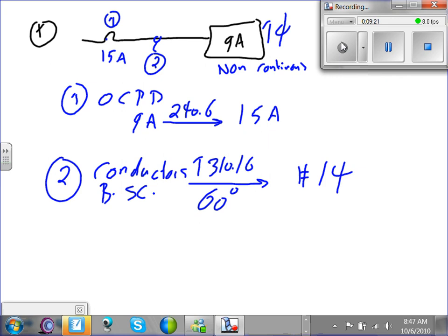If you take a hot and a neutral, what system is that? Single phase, a hot and neutral. So single phase can have 2 hots, or a hot and a neutral. How about if you put 3 phases now? It becomes 3-phase. Okay, am I clear about this? Or 2 hots. If you have 2 hots and a 240 load, is this single phase or 3-phase? Single phase. Okay, based on this, how many conductors do I need without the ground? Always without the ground, 2 conductors.